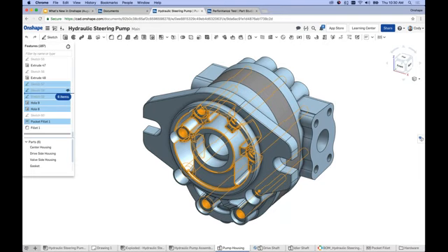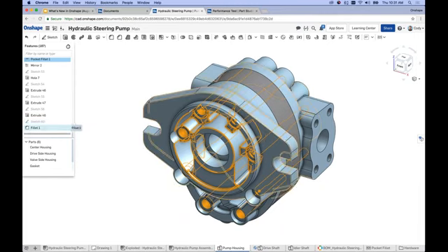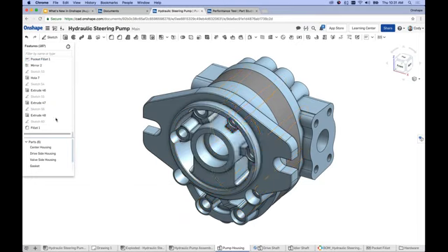What you'll see that's new is it tells you how many items you're dragging, in this case 6, and I can grab and drag them and move them up in a predictable way, right? And you'll notice all the features that I selected moved up, but the feature that was between the ones that I selected stayed still. So it doesn't have to be contiguous, right? It can be a group anywhere within your feature list. But the key is, again, just left clicking and selecting the ones that you want.